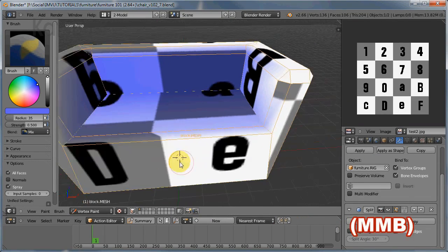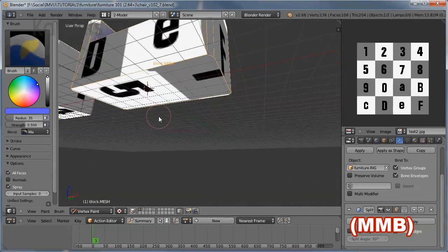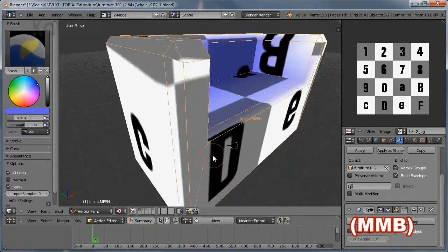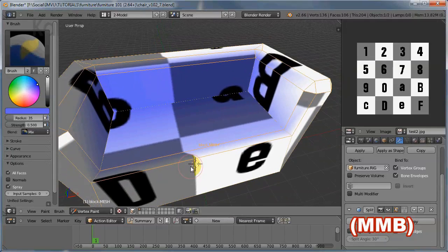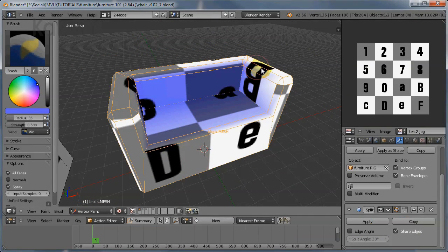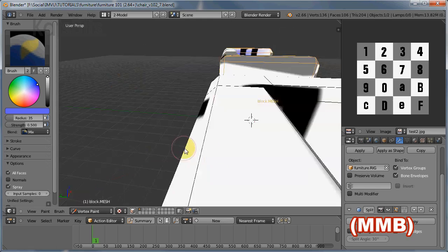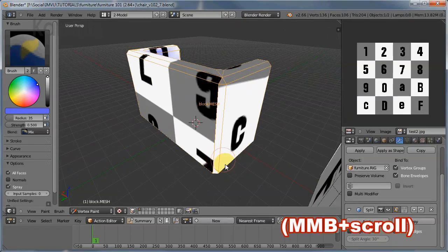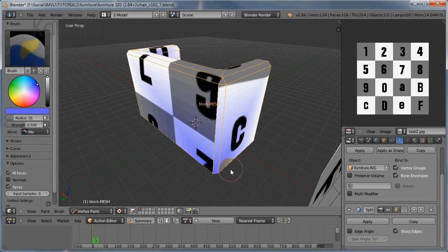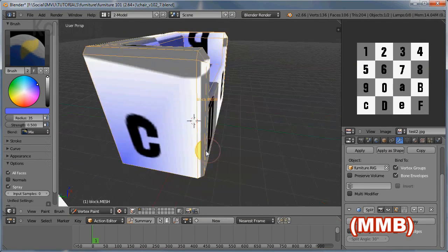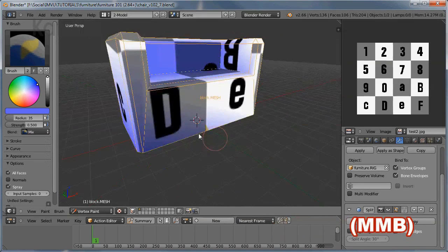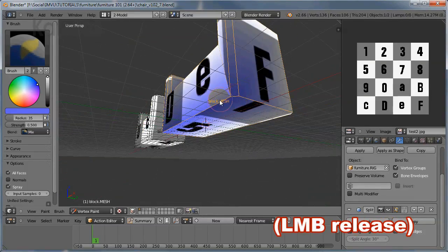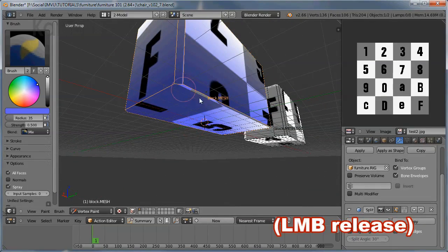Now the advantage of doing this is that we can use it to either tint a mesh or shade a mesh. So if there were a texture assigned to this couch and it were already a single colour, we can use vertex colours to re-tint the colours, changing it from red to orange or green to blue, depending on the colour that we paint to the mesh.